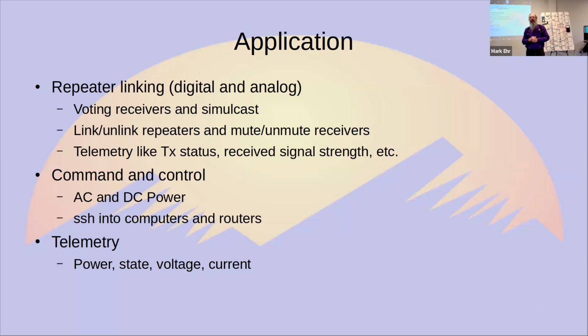You know, the rain fade is a bit of a problem. It's not super sensitive to it, but if you have a really big thunderstorm, you will probably lose the signal at 60 gigahertz. But you can get a gigabit through there. On 5 gigahertz, we're typically talking about 60 to 100 megabits per second on a good path.